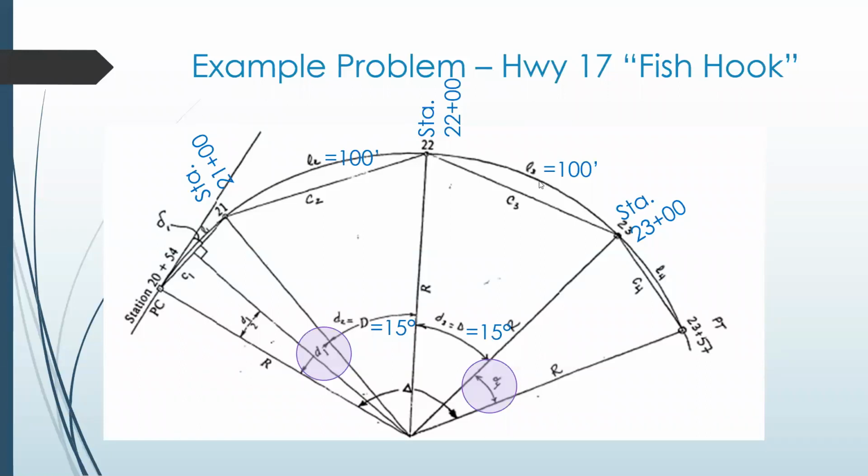For arc basis, wouldn't it just be 5,729.58 divided by the 15? Yes, it absolutely would. Nicely done. Thank you. Yes, that is perfect. So if we wanted to bang it out, prove out the theory, we could dissect our chord and our arc, say that our chord and our arc are close enough, come up with an angle, come up with our radius.